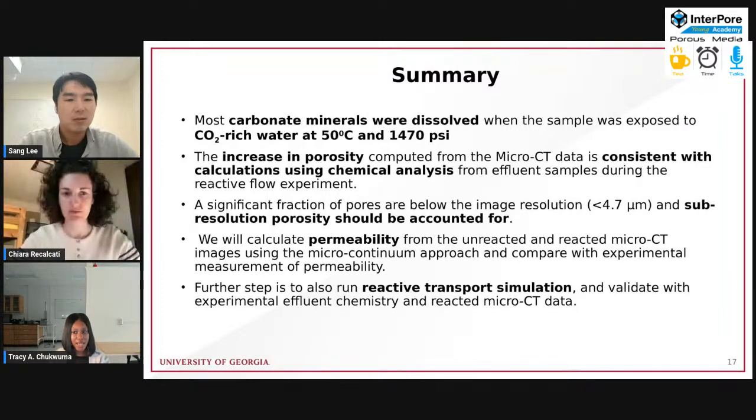For the stitching with the SEM, it is quite challenging because you have to be zoomed in and have this walkthrough pattern through the entire thin section. And you need to remember that is just one slice of the entire core. So at the end of the day, it's so labor intensive and it's just a 2D representation. For the X-ray micro-CT, you kind of already answered the question. It is really based on the size of your sample and the resolution you're going for. For the larger samples at lower resolutions that were taken at Auburn University, I'm not really sure about the time frame. But for the higher resolution, smaller samples here, it can take anything from about 24 hours to maybe slightly into your second day. So it depends on the resolution you want and the size you're working with, but to get something really good, sometimes it takes a while.